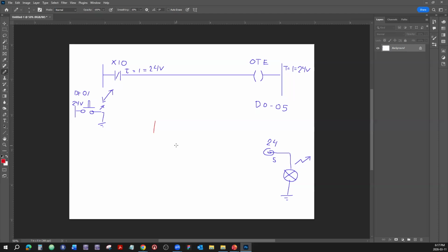We have red? Yes, we do have red. So let's say the switch is going to be pressed right here in red. Now, examine if open. Is the switch open? No. So the answer to the question is going to be false, which is going to give us logic 0, which is going to give us 0 volts on here.